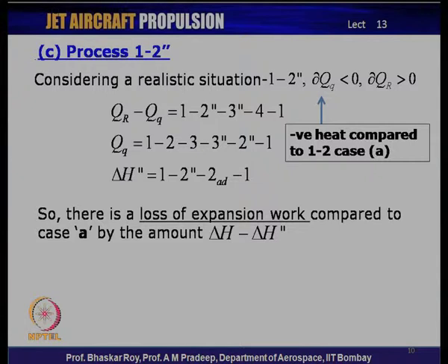So, when you are applying cooling for improving the life of a turbine, you are making a small sacrifice, that the amount of work that would be available polytropically would be slightly on the lower side. This is to be done in a knowledgeable manner, and this allows you to make a reasonable calculation and a priori knowledge of how much you might be sacrificing in the process of applying cooling to the turbine blades. So, those are the various obvious processes that occur in a typical jet engine gas turbine, and we would now like to look at a slightly more realistic gas turbine.